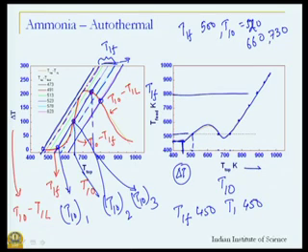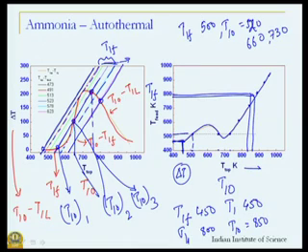But what about this point? If T1f is, let us say 800, it is not a very exact straight line. So, let us see, if T1f is 800, my T1 0 is something like 850, let us say. So, what has happened? Delta T is small here, and in fact, if you go even further, 900, the difference is almost vanishing. So, 900 T1f, T1 0 is also 900.